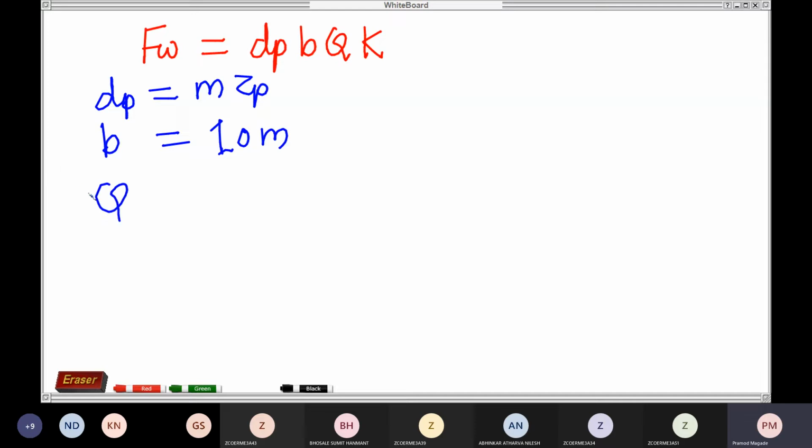And for considering the ratio factor, we need to consider whether the gear teeth are in external mesh or internal mesh. External means the teeth are externally meshed. Generally 99% of cases are external mesh. So that is twice of ZG divided by ZG plus ZP. So that is the ratio, and for the internal gear, we'll have to consider a minus here.